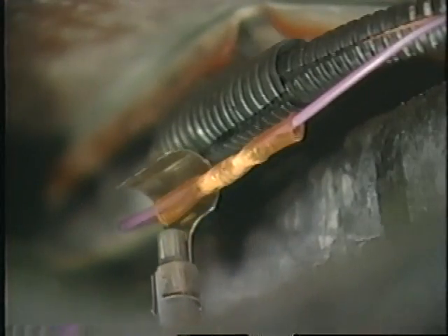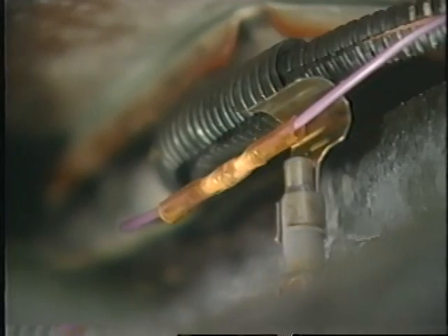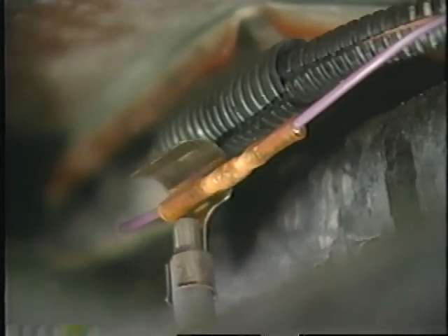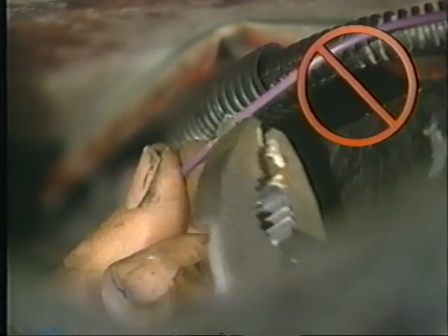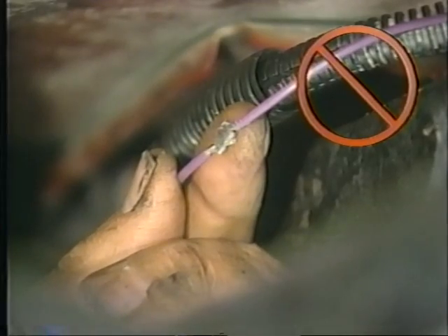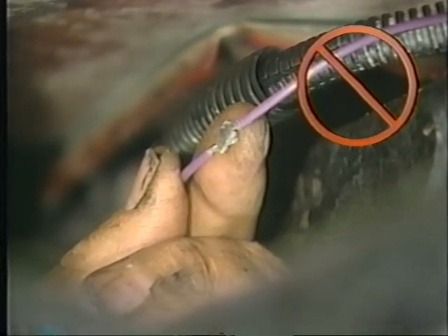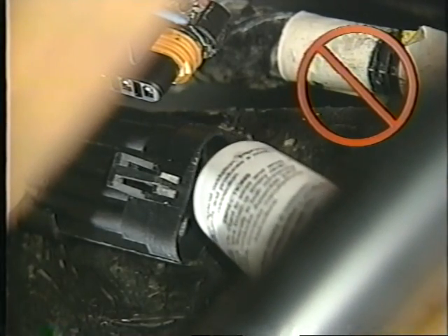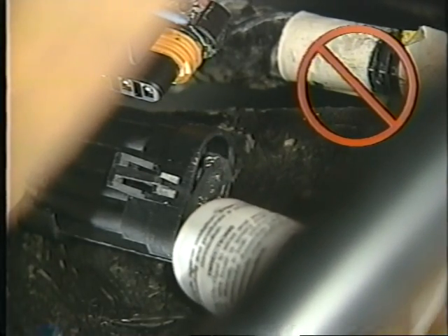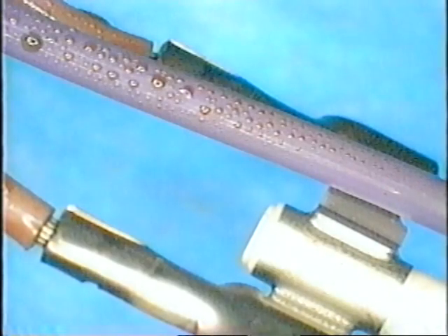Now, use the ultra torch in the kit to heat the splice until the wrap shrinks and glue melts out of both sides. Do not use any other splice, and especially do not, repeat, do not solder the connection. Doing so will impede the air path through the wire. Here's another thing you must not do. Do not install any kind of grease into the connector, not even dielectric grease. Grease will migrate down the wire and contaminate the inside of the sensor. Even a little bit is catastrophic.